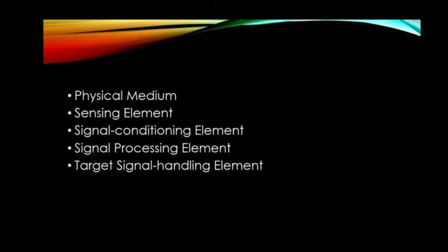In the more common case where the sensing element comes in contact with the medium, often some physical or chemical property of the sensor changes in response to the measurement variable. This change then becomes a measure of the physical variable of interest. For example, change in resistivity due to heat in a resistance thermometer wire, or generation of voltage in a thermocouple in response to a difference in temperature between its two ends.